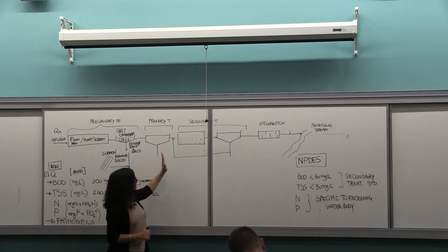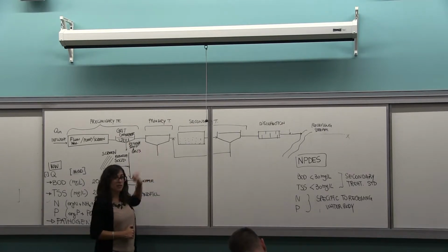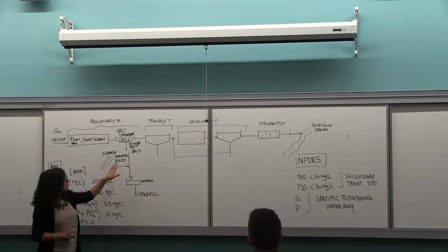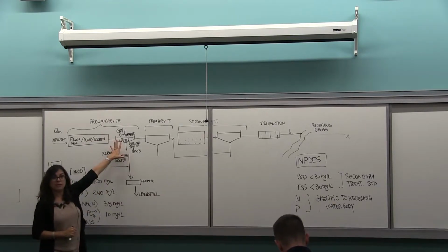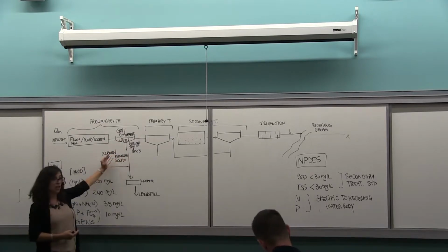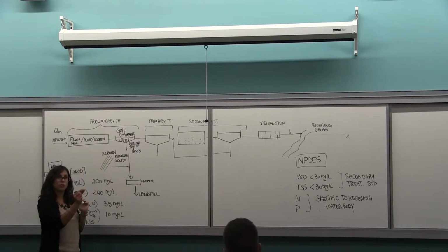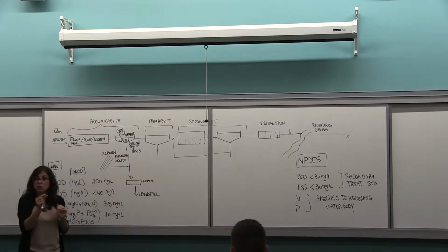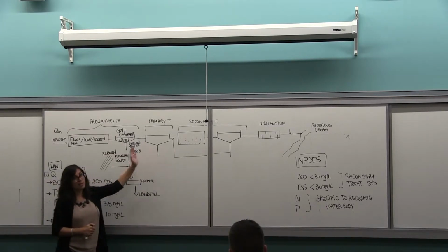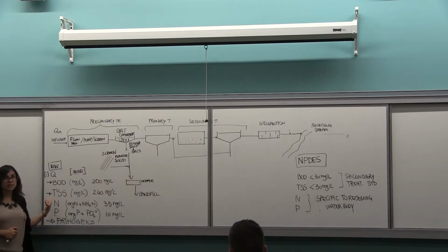After this, we're still removing solids. However, these are solids that settle in a couple of minutes, or are not large enough to be retained by a one inch or half inch opening in a screen system. What we care about here is removing suspended solids.